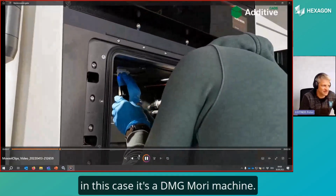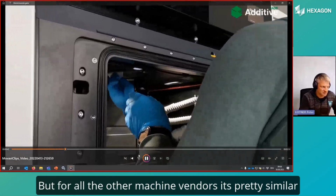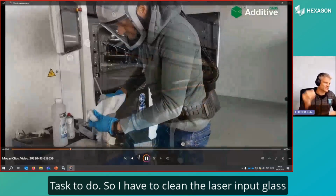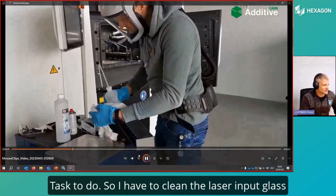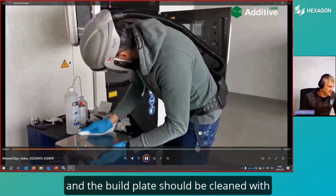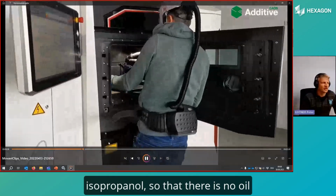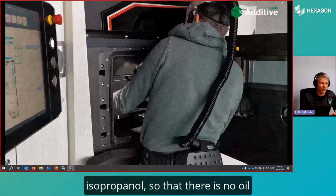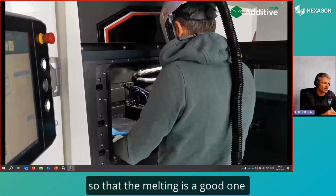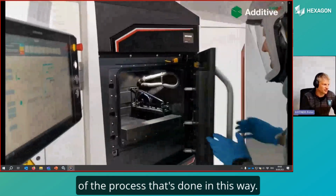In this case, it's a DMG Mori machine, but for all the other machine vendors, it's a pretty similar task to do. So I have to clean the laser input glass, and the build plate should be cleaned with isopropanol so that there is no oil or something like that on the base plate, so that the melting is a good one in the process, let's call it this way.